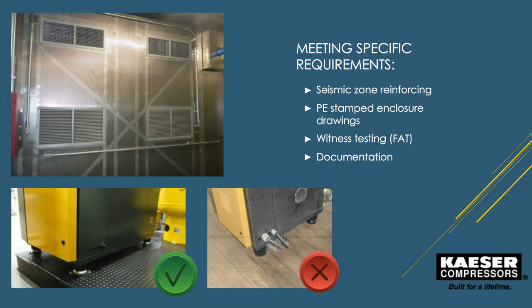You can see in the lower left an example of how to properly anchor a piece of equipment to a steel structure or skid, such as machine mounting feet. You can see on the right what we typically would see in the field. We would see the compressor just placed in a shipping container and no precautions or preventative measures taken to keep the unit from moving.